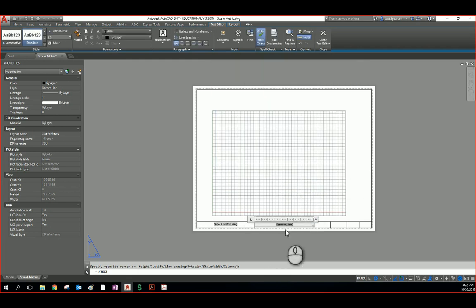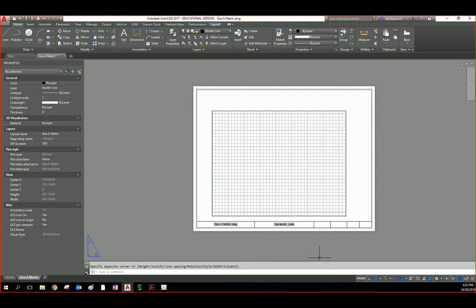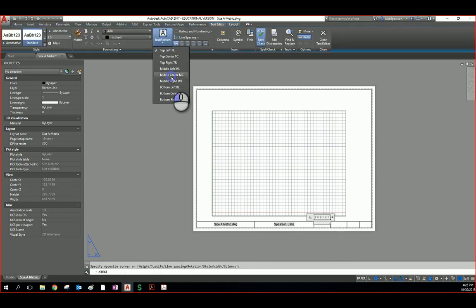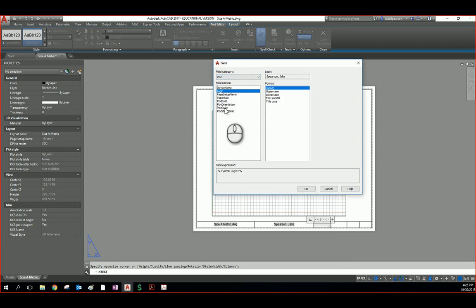Boom. I'm going to go ahead and Control A to select it all, or I can physically scroll it over and then change it back to my 3.175. You're going to get all these measurements if you go back to the template, the size A drawing sheet, and scroll down to metric. I'm going to go size A. There it is, center middle. This here is going to be the plot scale.